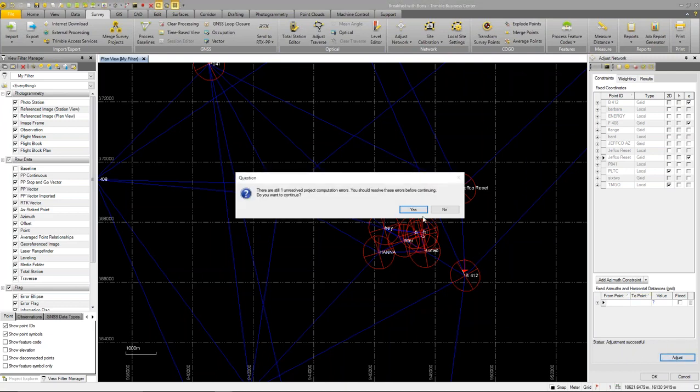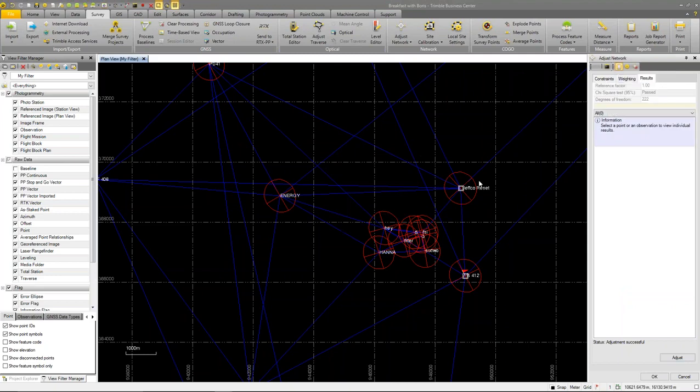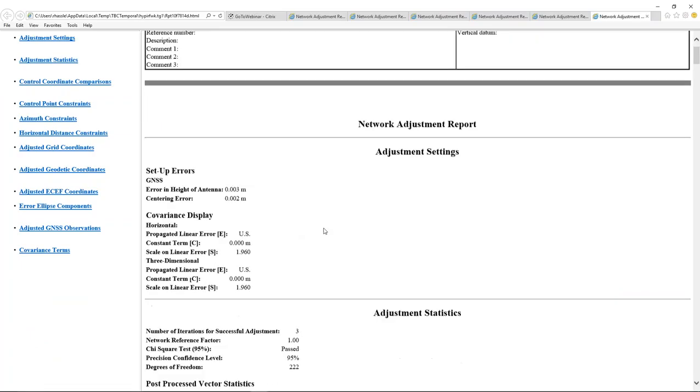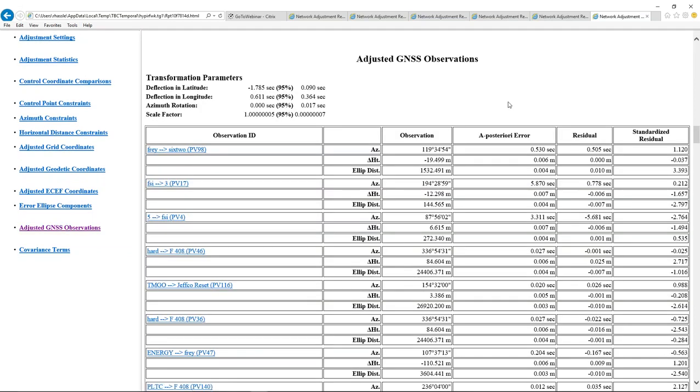And when I do that adjustment, what you'll see in the adjustment report is that I really, again, haven't changed my statistics on the adjustment at all. All I did was rotate it, scale it, and now I've tilted it a little bit to try to fit my control perfectly. And that meets the minimum number of constraints necessary to calculate all of the transformation parameters that will be applied in the coordinate system definition after I accept this adjustment.